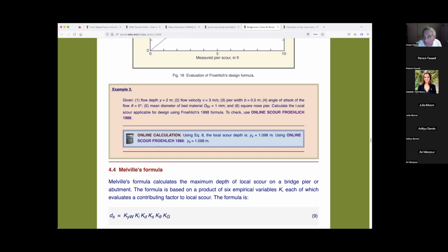Typically, as I already said, it is a 500-year return period. It assumes, of course, that the flood, subject of the calculation, is going to happen once every 500 years. It does not mean that it will take 500 years to happen. No. Technically, what it means is that if it does happen tomorrow, it will take another 500 years to repeat itself, the size of that event. But it can happen tomorrow. So that's why there are failures in hydraulic engineering, because we're unlucky. I chose 500 years and all of a sudden the event happened tomorrow.